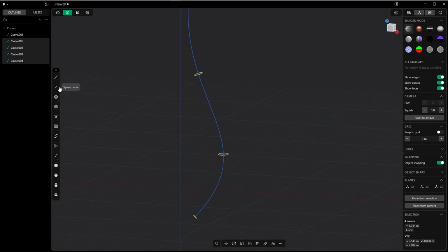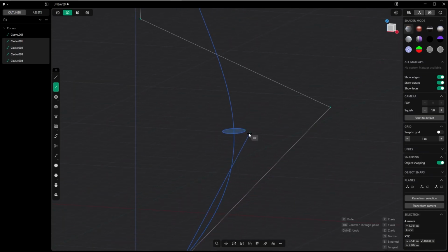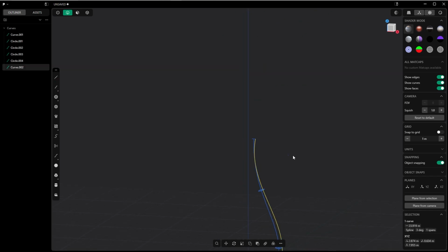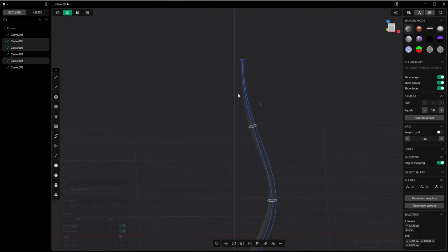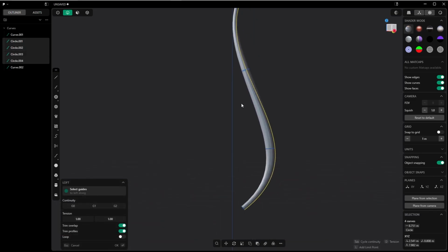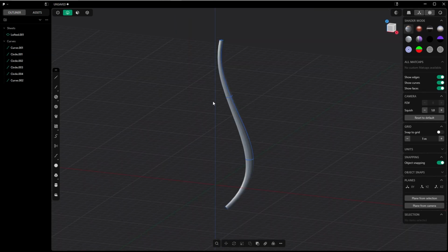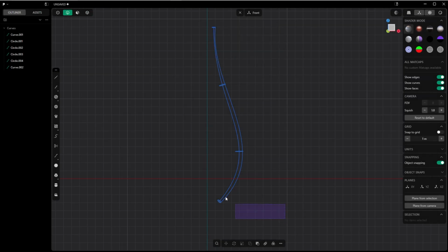but I will test also another way, and that is creating a guiding curve with the spline curve, snapping at the edges of these circles. So let's again loft, selecting the circles one by one, and now I will select my guiding curve, and here you can see that I get a much more beautiful curvature. Okay, that's okay, but I will delete this sheet I have created with the loft and continue creating some curves.